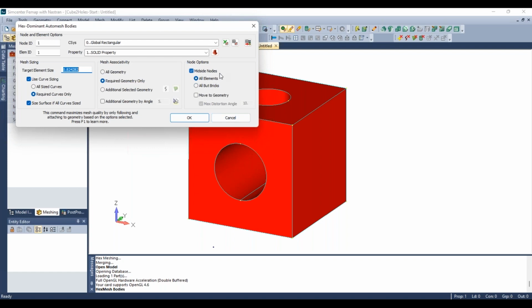So you're going to be getting 20 node hex elements when you do this, which begs the question of why you might want to do that. The 20 node hex element still has 6 nodes less than a cube made out of tetrahedral elements. So you are getting a 30% advantage in node count by using the 20 node hex over a pure tet mesh. So that's one thing to consider. Should we show it on or off? Yeah, let's just go all defaults here. Let's see what.